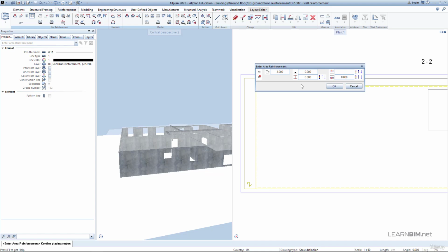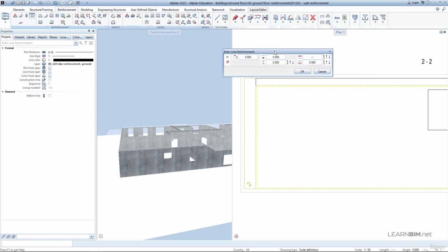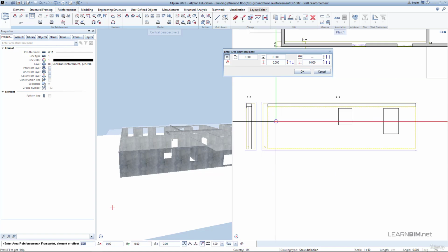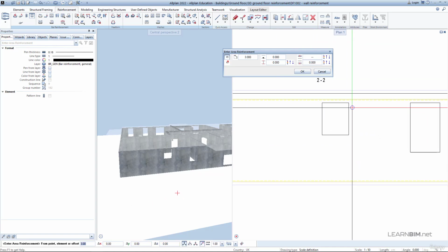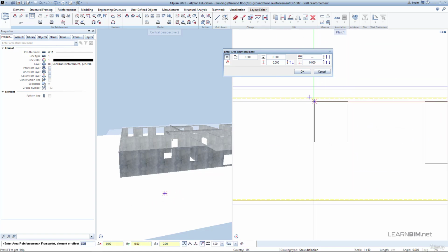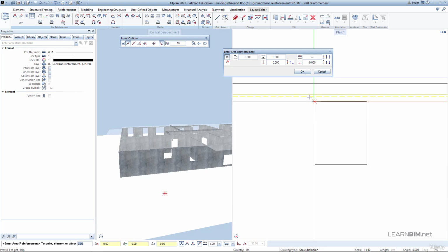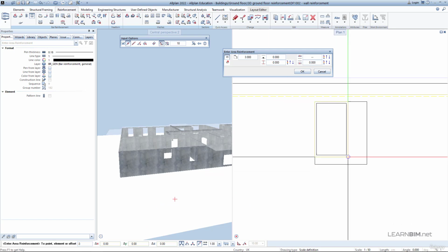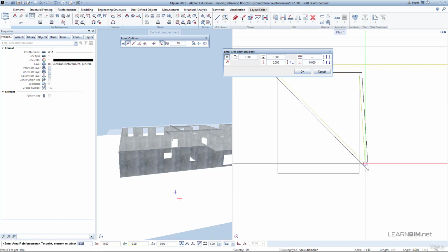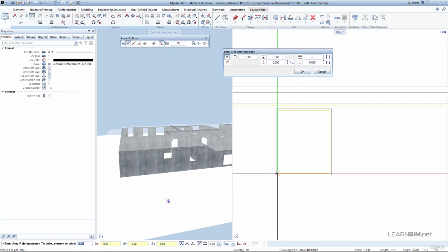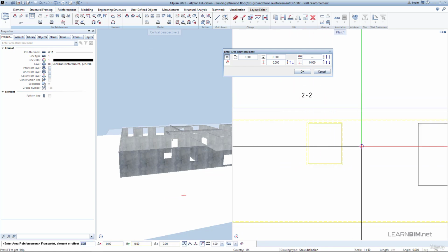At that moment, you can check and input new parameters in a new pop-up window. First, in the upper left part of the window, you have the option for entering the openings. Select it and input the edges of the window opening. In this case, you need to change the offset to -3 because now the black concrete cover line is inverted. Input just one window opening. We can do the changes for the other opening later.